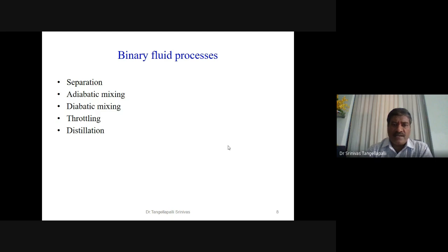That's why steel or even mild steel is fine. Some other materials we have to use, but with lithium bromide water there are no such issues, it's not toxic and at the domestic level we can use it. But the problem is, as of today, lithium bromide water is developed for cooling purpose only.